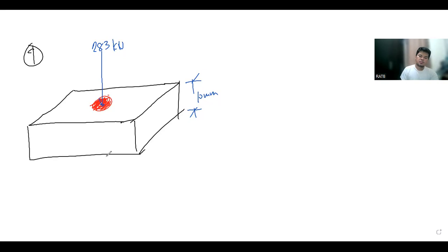And then the required diameter is 20 mm. So what will happen here is that after punching, this part will be removed from the plate. So meaning to say there will now be a hole in this plate. So the item is asking for the shearing strength, no? So that is force divided by the area.